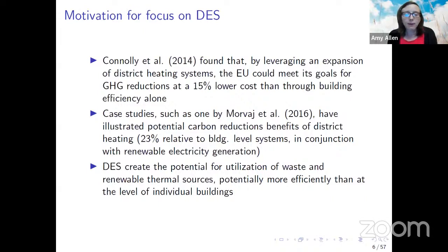And that results from the fact that 5G DHC systems can use, in some cases, uninsulated plastic pipe due to their more moderate operating temperatures. And also, since they generally provide heating and cooling from a two-pipe network and permit buildings to offset each other's loads, they can provide both heating and cooling more cost effectively than conventional district energy systems with separate heating and cooling networks.